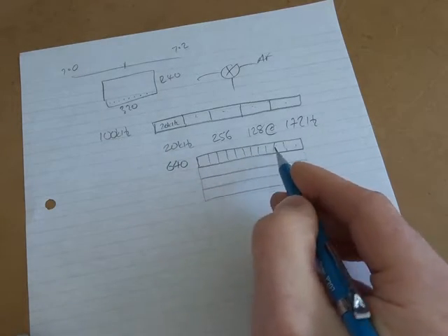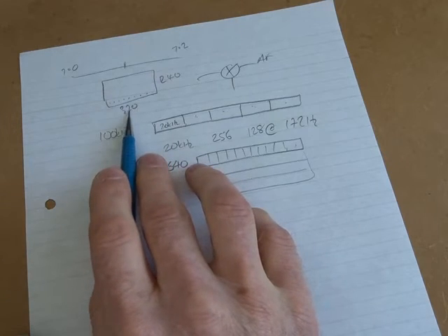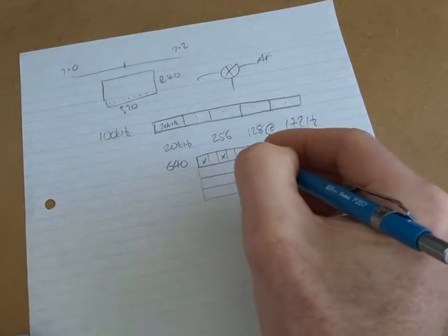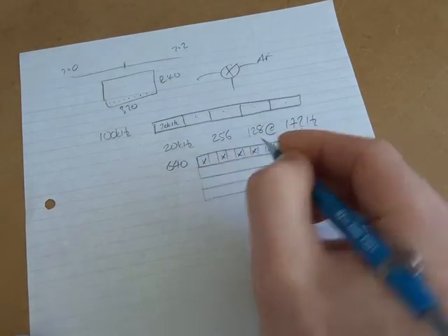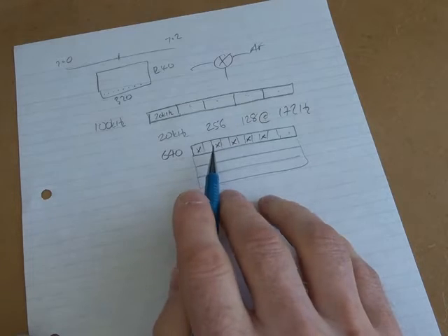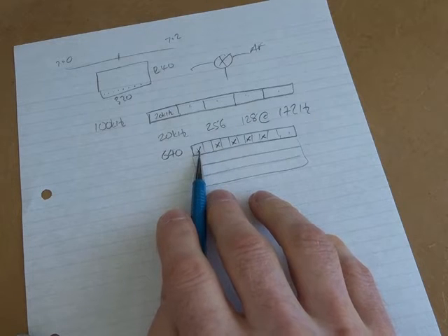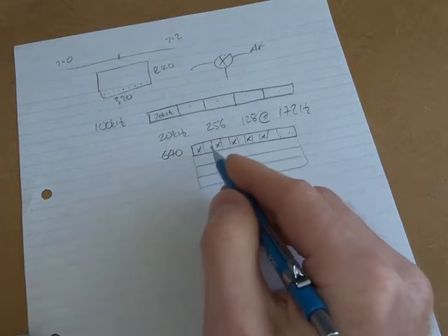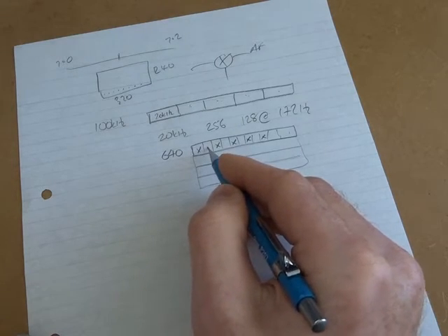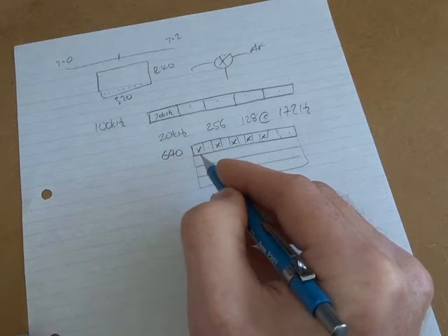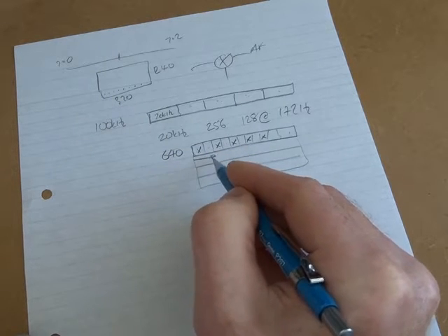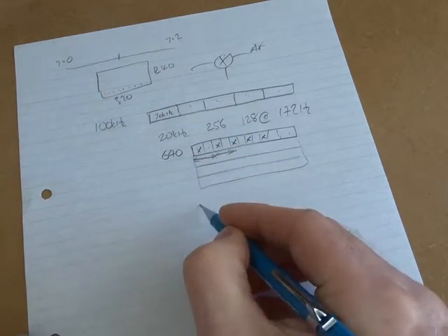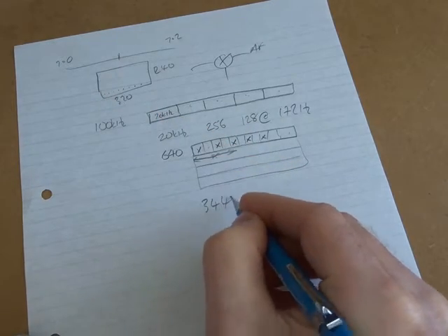Now our display is only 320, so I'd have to only display on the display every second bin. So that would be what I'm looking to do. If that's the case, then it's going to be 172 times 2, which is 344. Because I'm missing 172 there. So this particular element on our display would have to represent 344 hertz.